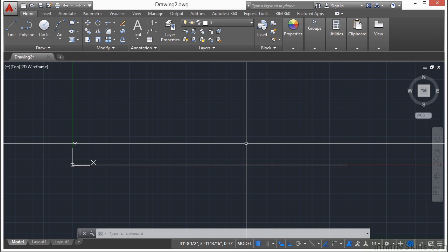When you're working in architectural units, you draw in inches. Now, there are 12 inches to a foot, so 12 times 50 is 600. You can type in 50 apostrophe like we just did for our 50-foot long line, or you can also type in 600, which is 600 units, which is 600 inches, which is 50 feet.